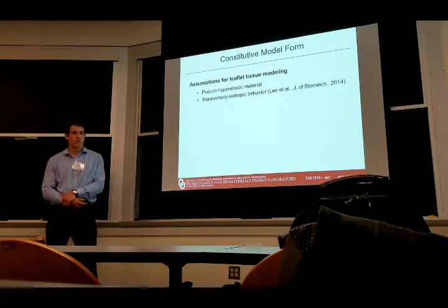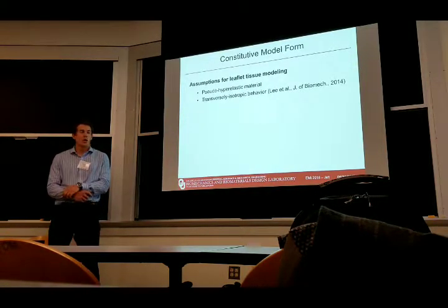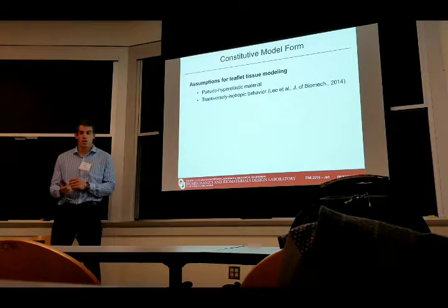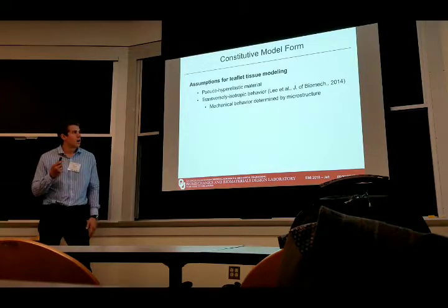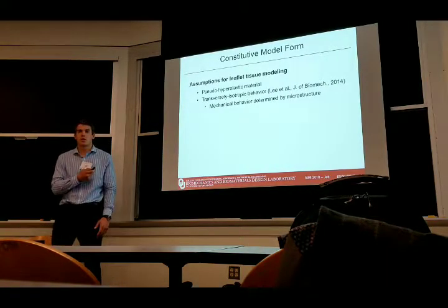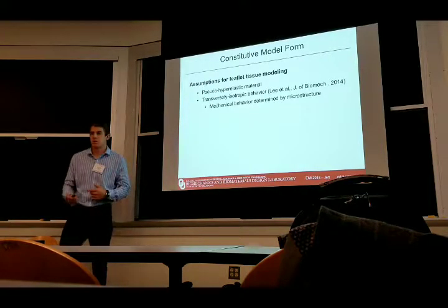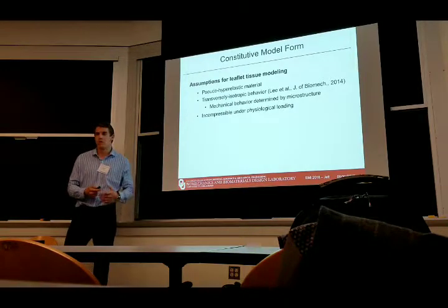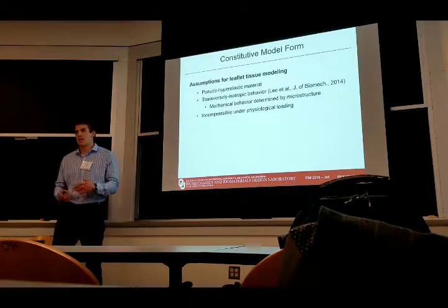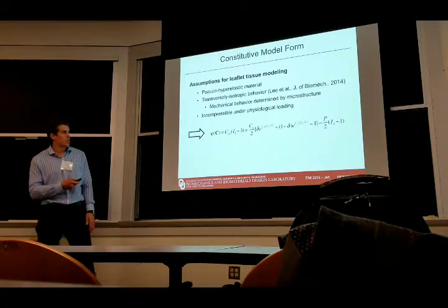We also assumed this was a transversely isotropic material. This was based on an assumption made in a paper by Dr. Lee and others, and this actually produced pretty valid results for fitting of leaflet mechanical responses. In that assumption, we looked at the microstructure of the material and related the mechanics of the material to the microstructure through an inverse method. And we also assumed an incompressible material, which is very standard, based on the high water content within the tissue as well as other reasons. And this led us to the form shown here.